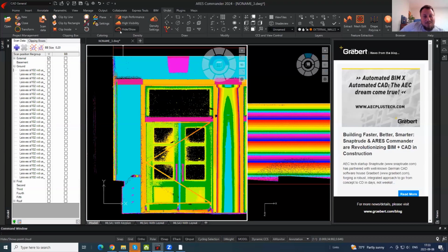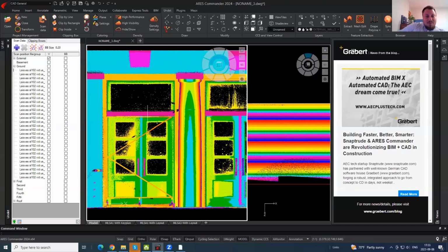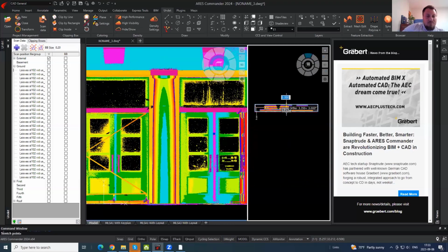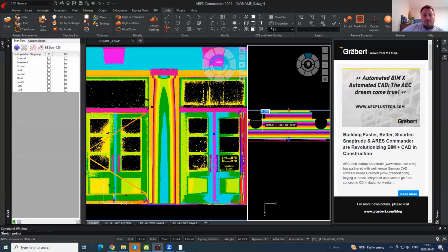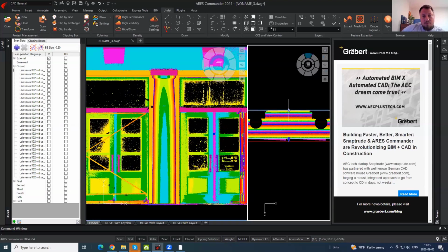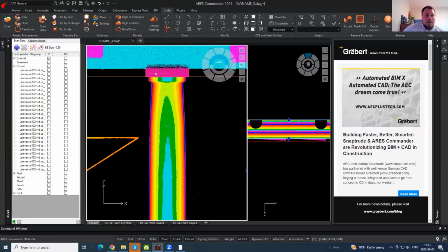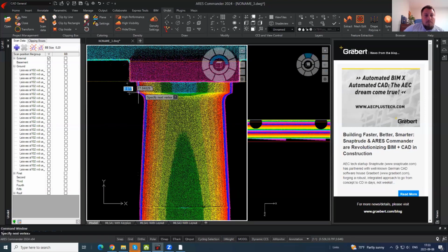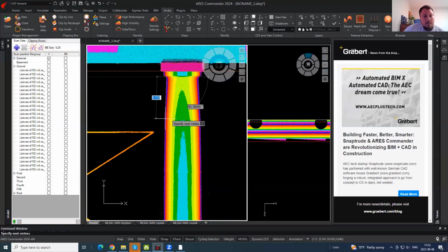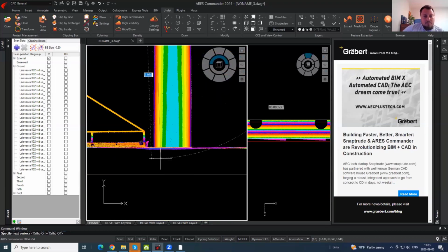And I'm telling you why, because you will not use those colors if you only need to produce 2D drawings. You don't need those colors. You can color by plane. Of course, when customers ask to deliver a point cloud, you can ask if they want true colors, but for the vectorization process, as you can see, we don't use any coloring mode apart from coloring by plane. And then you can set the fixed size interval and just get a clear view of elevations.